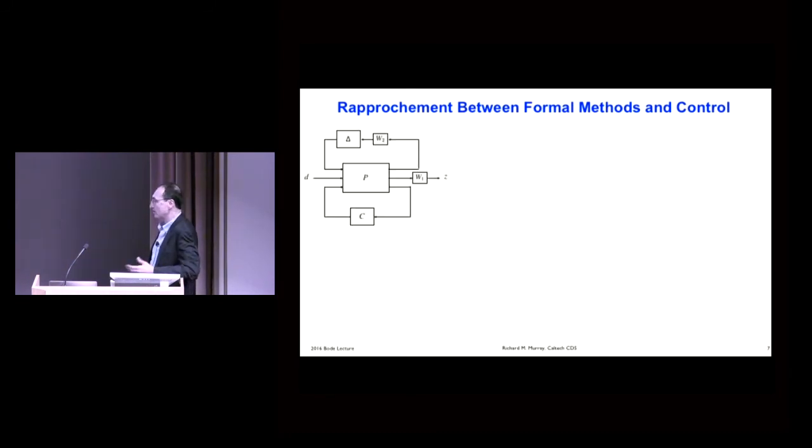But there's an interesting thing happening, which is that if you look at what control theoreticians would typically write down as a typical control problem, they might do something like this. I've got some process dynamics, I've got some disturbances that come in, I have some outputs that I want to regulate, I may have some weighting function like frequency weights, what are the frequencies that are important to me, and other things. I've got some disturbances, those are often operator-bounded uncertainties. This might be I don't know the flexibility of the wings exactly, or I don't know the dynamics of the building exactly, and so I'll put those dynamics in as some sort of an uncertainty block, again with some frequency weighting, where do I know things, where do I not know things.